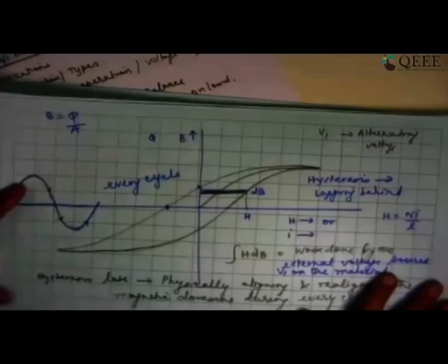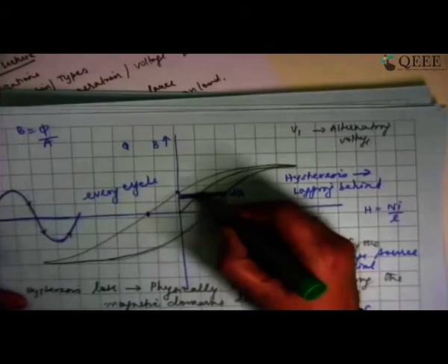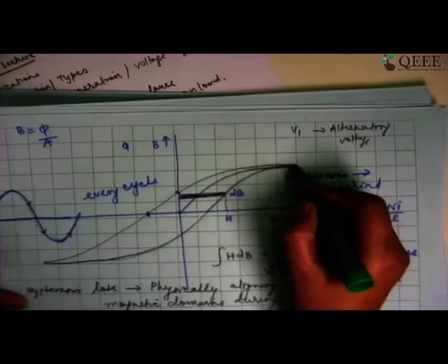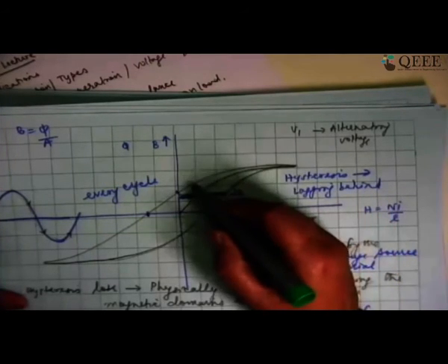Coercivity and BH loop. Okay, fine. There is a question regarding coercivity and BH loop. Let me take that BH loop diagram itself and then explain coercivity from there. So here is my BH loop diagram. If I start with a new sample of iron, it is going to start from 0 current and 0 flux. It is going to go towards saturation. It reaches saturation and then it starts coming back.